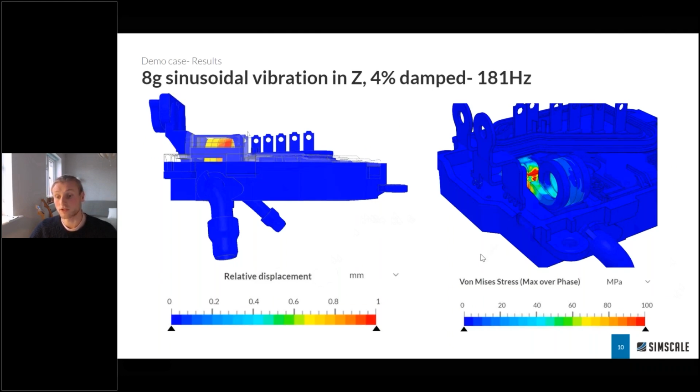Okay, so then we can start to really understand, hey, is this maximum vibration amplitude going to cause clearance issues? So is there going to be rattling? Is there going to be noise? And is this part likely to break because of the high stresses in the model? Okay, so we're starting to get up to some pretty high stresses here. So in this case, we may need to consider design changes, but already having this information up front allows us to really understand where is the vibration risk in our product.